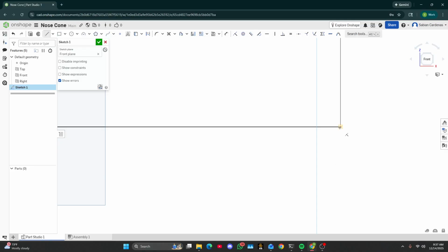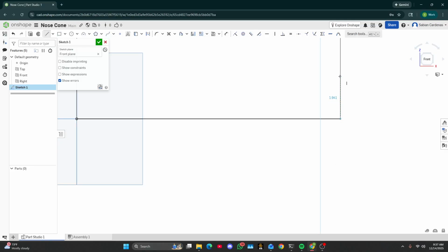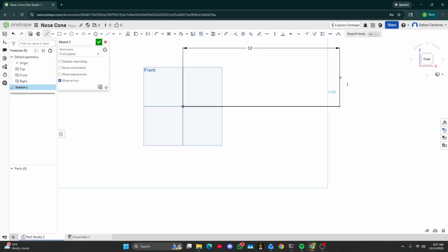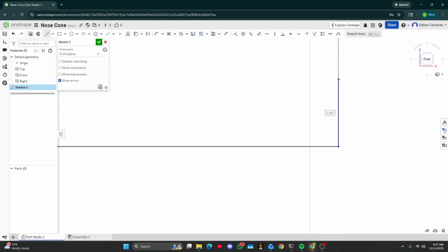We're going to start off with creating the shoulder, which is the connection point, or the sleeve that goes into the inner diameter of the body tube, and that will be 1.5 inches. We're going to extend it out to be, give me a second, let me refer to my OpenRocket. Yeah, we're going to make it 2 inches.